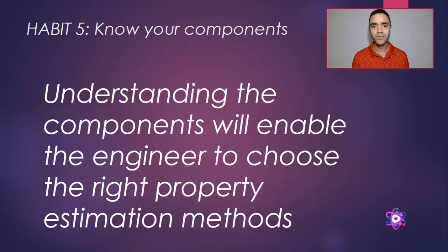And moreover, sometimes we have fluid packages or property estimation methods that do not fit one with another. When I'm dealing with gas sweetening, for instance, sometimes I need to use for my gas stream a fluid package that is not compatible with other components that are available in my process simulation. So knowing your components will help you to choose the best fluid package for your process simulation.